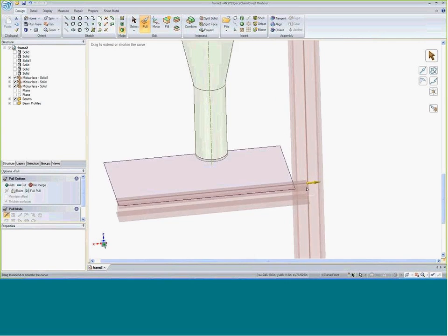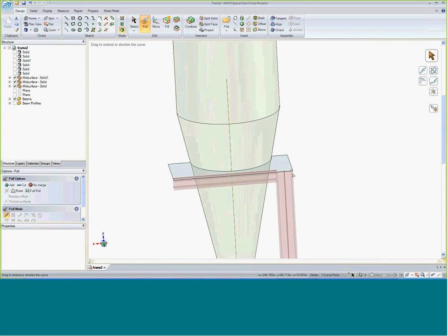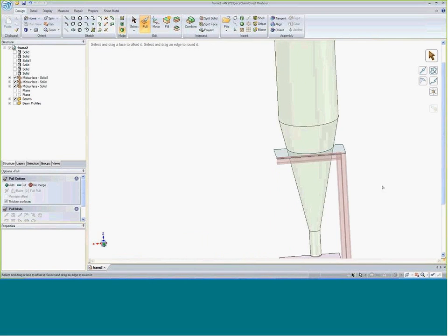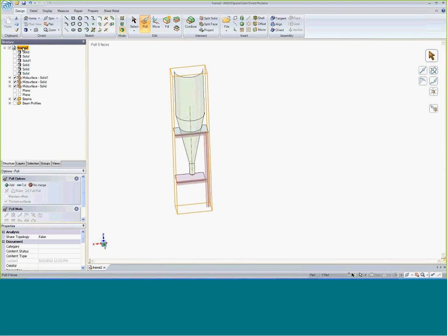So you can see the plates in there, and those are connected. And then one last connection here. I'll just manually do this. I'll click these to each other. This is good. Everything is now touching at this point. I want these to be meshed all continuous when I bring them into Mechanical. I just need to do one on the assembly level of this part to just say to share the topology when I bring that over.